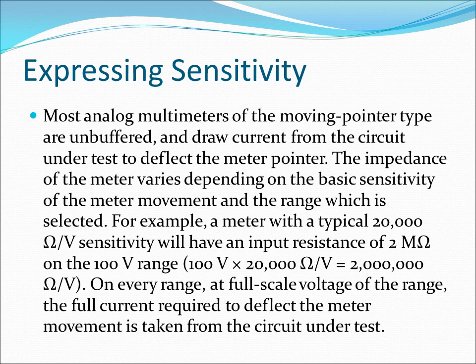On every range at full scale voltage of the range, the full current required to deflect the meter movement is taken from the circuit under test.